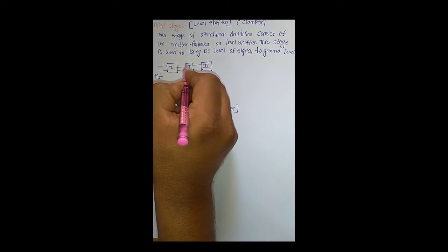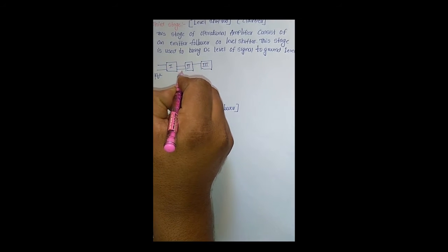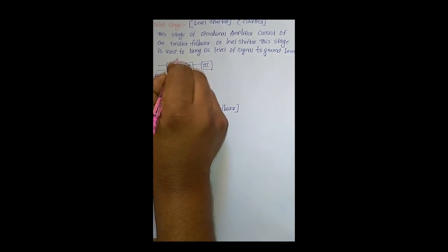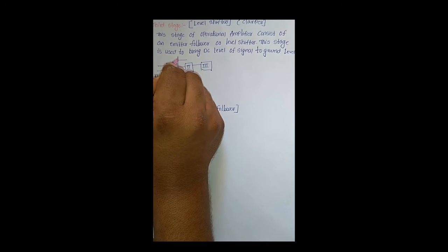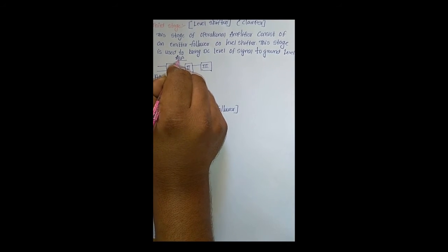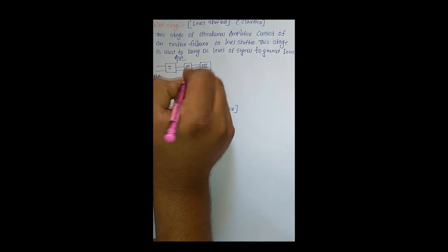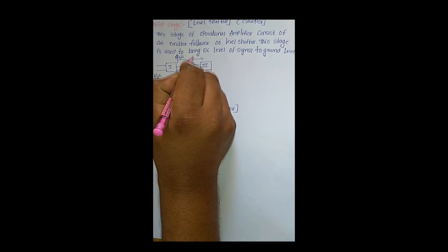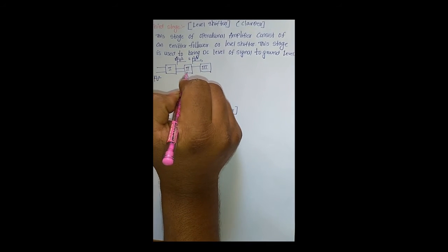After performing the differential amplifier operation, here we will get the output with some DC level added. This is the output signal, and here the DC level is 1 volt. This output is given to the input of the second stage. Again this differential amplifier adds some DC voltage, so we get the output with 2 volts DC, and the signal is amplified like this.